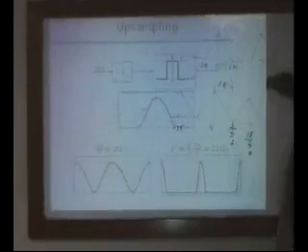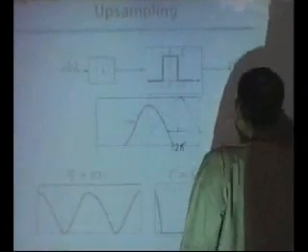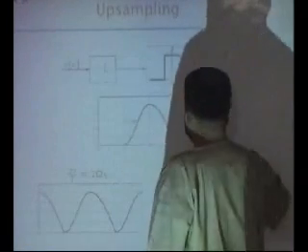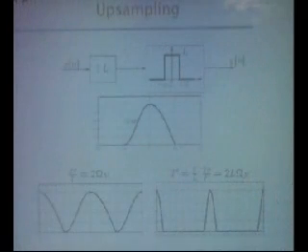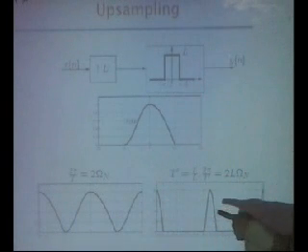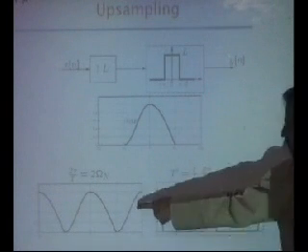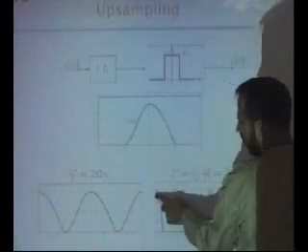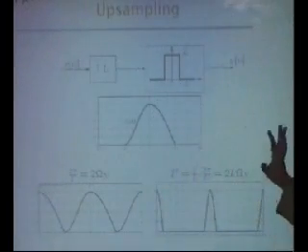If you insert zeros in upsampling, and you can try this in MATLAB as well, inserting zeros means simply dividing the spectrum, and this is what is shown here. This is what you want in interpolation: this 2 should go to 8 if you are interpolating by 4.